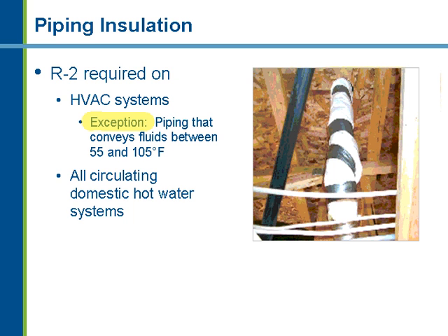But anything that's carrying chilled water, which is going to be typically below 55, or warm water for heating above 105, is required to have the R2 insulation.